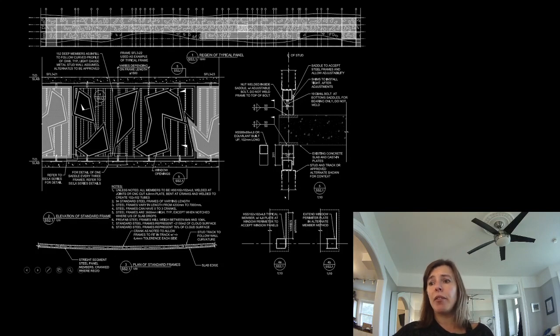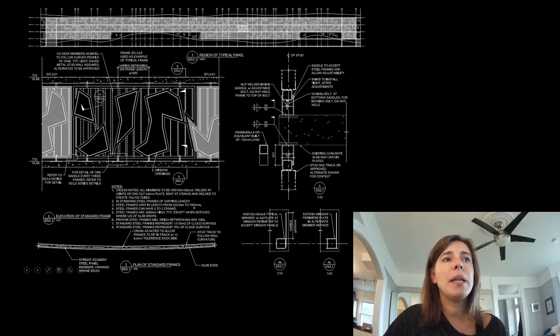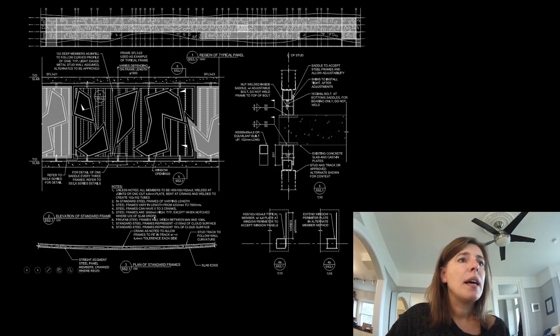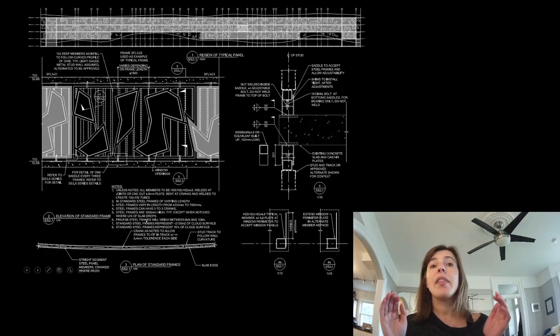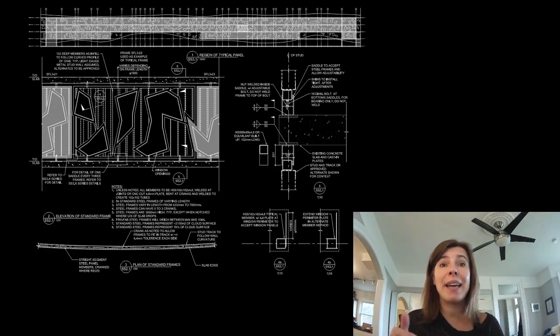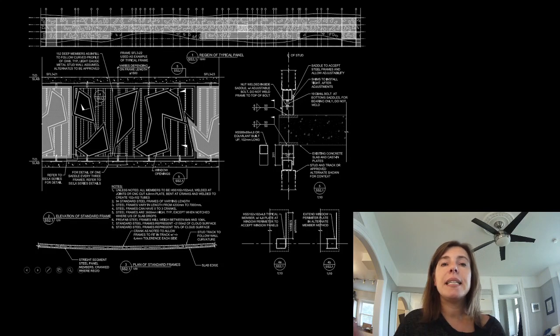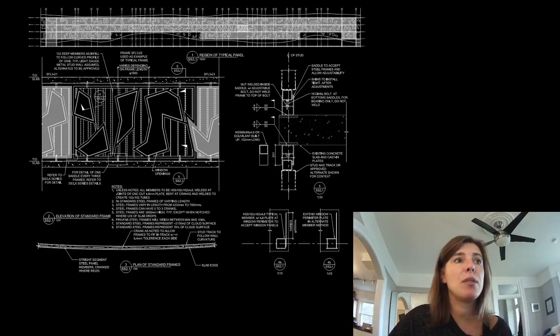I listed criteria for AESS for the panels, for some small spots that might have been visible. And then you can see the panels varied from 4.2 meters to 7 meters in length. They also have the height of the panels. These all also needed to be trucked to site, so they had to fit on the back of a flatbed. That was a big criteria within it. So the top of a panel compared to the bottom of a panel needed to fit on the back of a flatbed, which is about 3.6 meters.